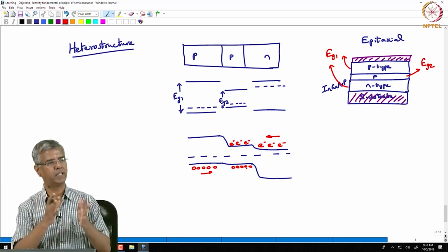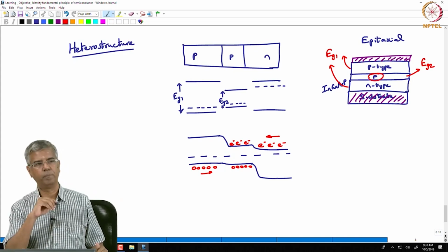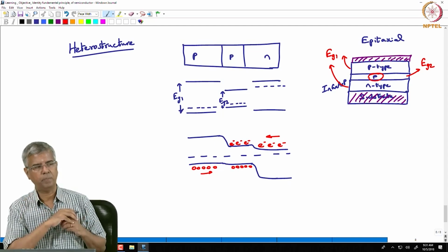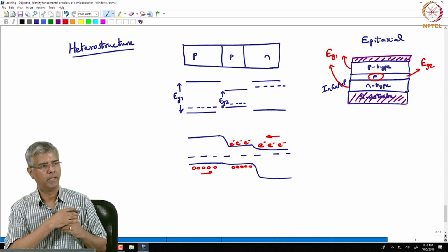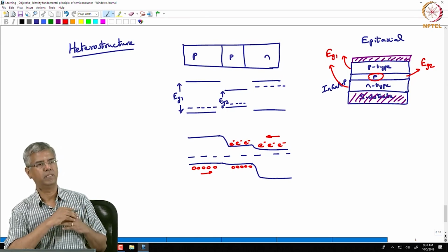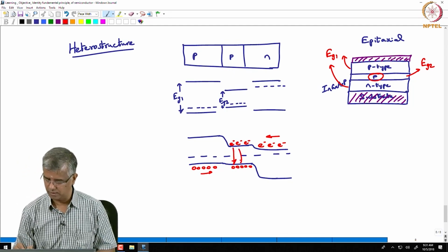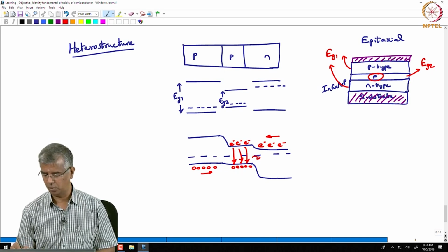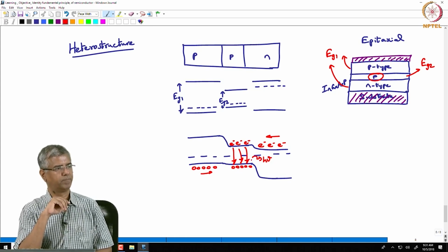So everything gets accumulated essentially in this p-type region, right, and at that p-type region it has nothing else to do but to recombine between themselves. The probability of recombination increases quite a bit in this sort of structure. So then in this region you have all this recombination happening, and because of that you have light emission.